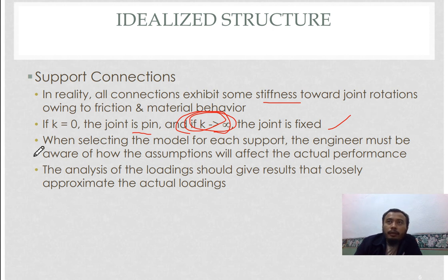So some of the designers in America, if it is a steel structure and the connection has some value of restriction against a moment, they would consider a certain value of forces being converted into moment. But in this subject, we only concern with the idealized structure. But later on, when you are working, this needs to be put into consideration.